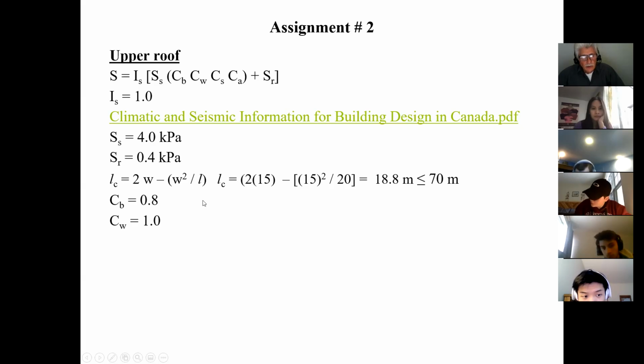And of course, the CW, like I told you, this is a normal building. There are other values, but don't bother taking the sweeping effect, because you have to guarantee that that wind effect blowing the snow off the roof is going to be there within the life expectancy of the building, and that has to be there for at least 60 to 70 years under that condition. And all of a sudden, the condition can change, and you would be responsible. So I strongly recommend that you always use 1.0.